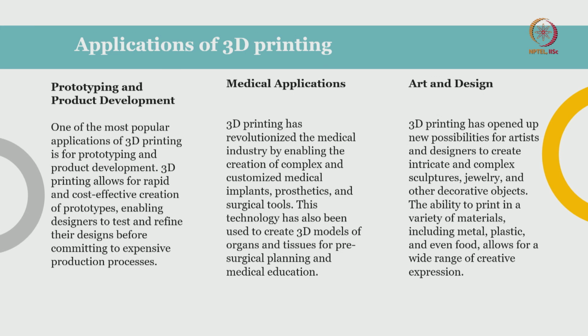Now we have 3D printing technology. If you need to make three different models, you can do all at once. As I said earlier, if we have three different varieties of the same object, we can place them on the same print bed and get all three versions at the same time. Once we finish designing the model, we can put it for printing, and depending upon the print size and print bed, which depends on the printer, we will get it within hours or even within a day. That is the main advantage in the prototyping industry.